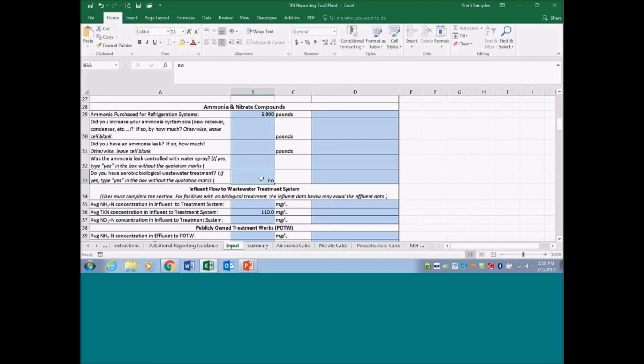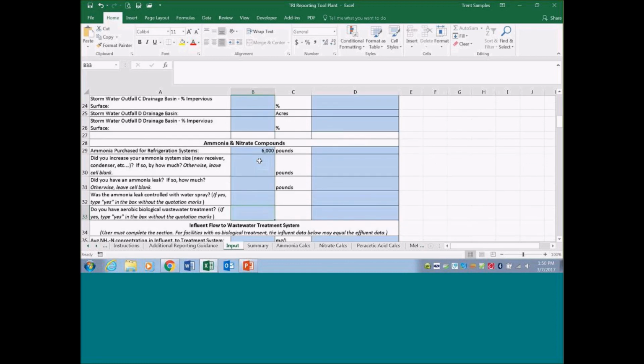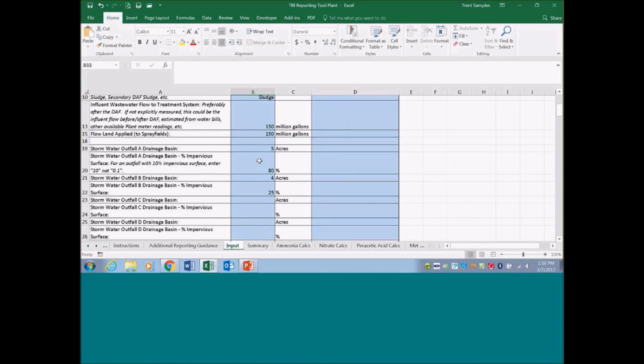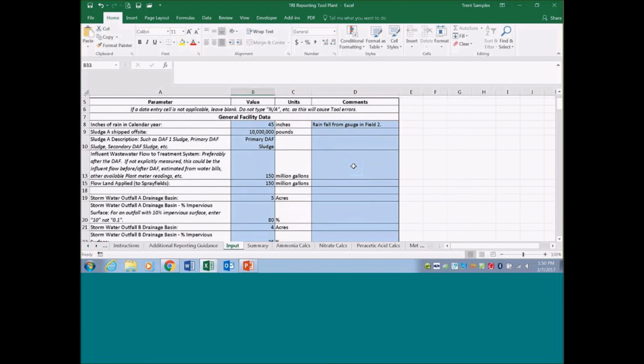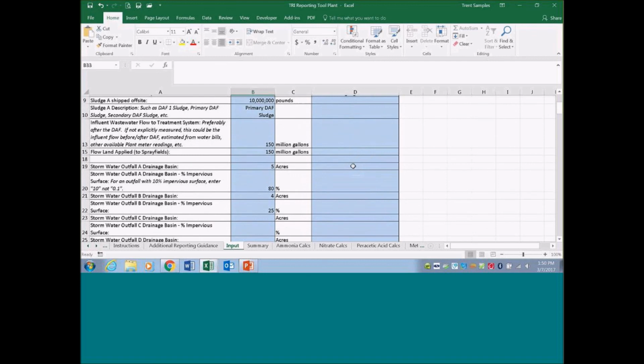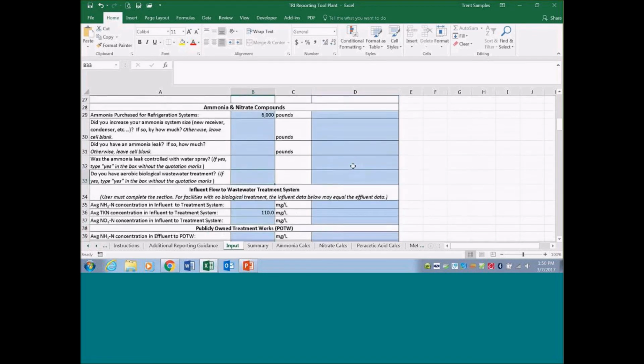It's important that we consider the biological treatment component, because that's where the ammonia can be generated, and then that's where the nitrate can be generated. If you just have a DAF or some pretreatment system, generally you're not going to get that conversion, generation, or release of significant amounts of ammonia and nitrate. It's that biological treatment system where you're generating those other constituents.